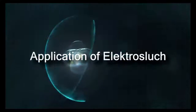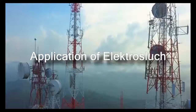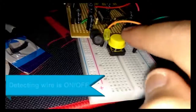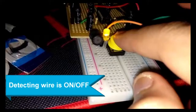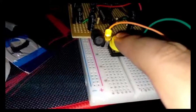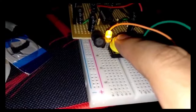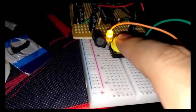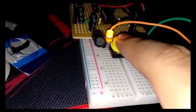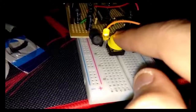For the application, there are three types of application that we can use the Elektrosluch to detect the sound of electromagnetic field, or EMF. The first application is to detect the connectivity in the wire. As electronic engineers, they need to identify if the wire has current flow or not. So the Elektrosluch can detect and produce sound if there is a presence of electromagnetic field. If there is a sound of EMF, it means there is a current moving in the wire.